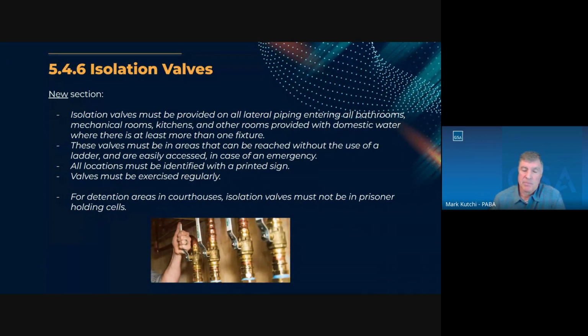I think this requirement is going to add more piping. As you said, it typically comes overhead. It's going to have to loop down to an accessible location before it feeds the individual fixture. So it's probably going to require a few more feet of piping in most situations to get to an accessible valve box in the wall, so you can reach this isolation valve.